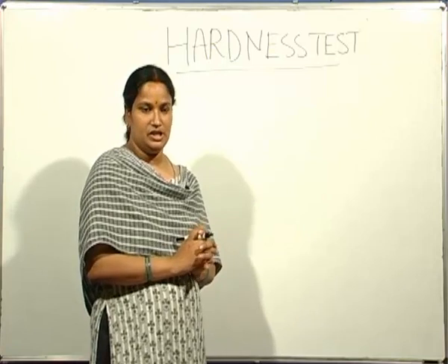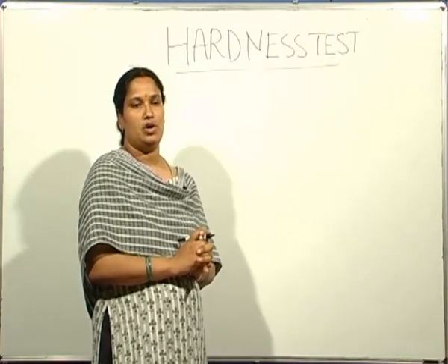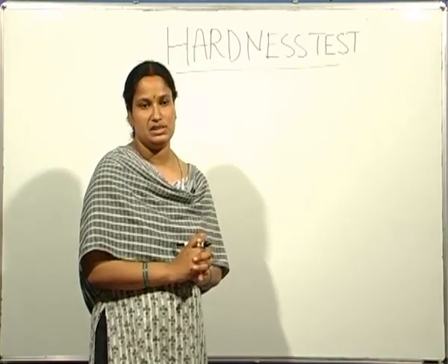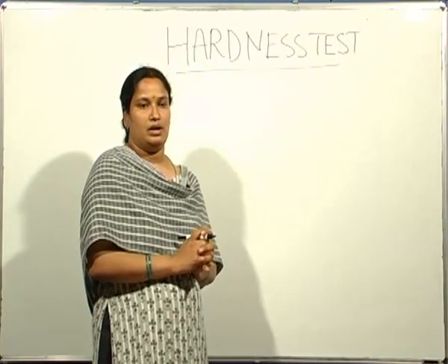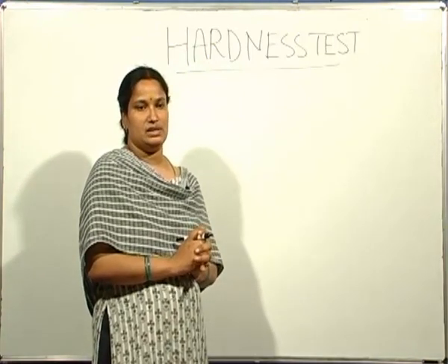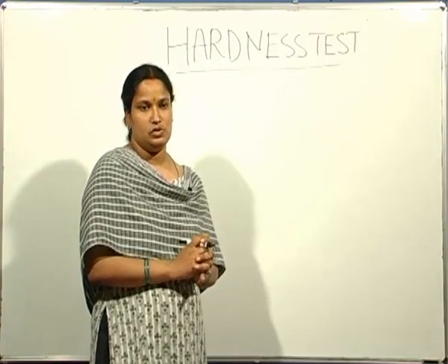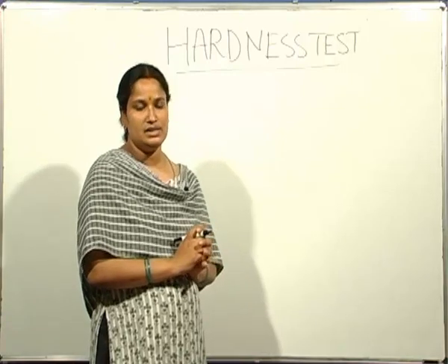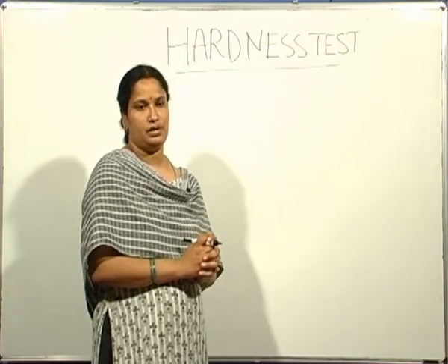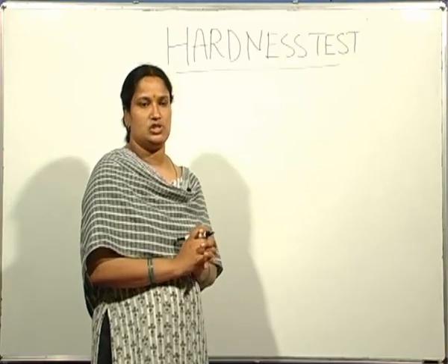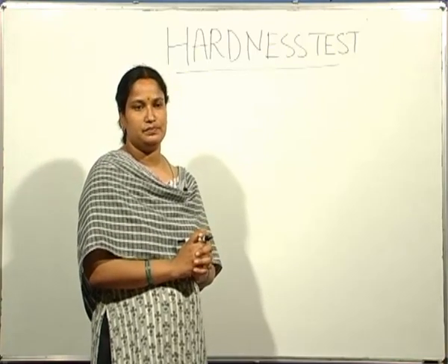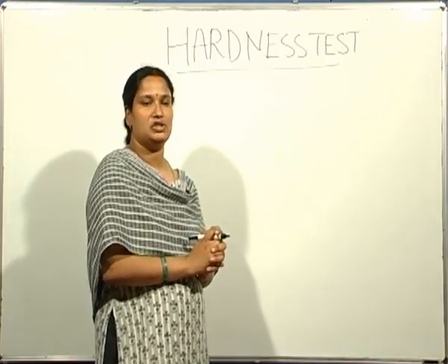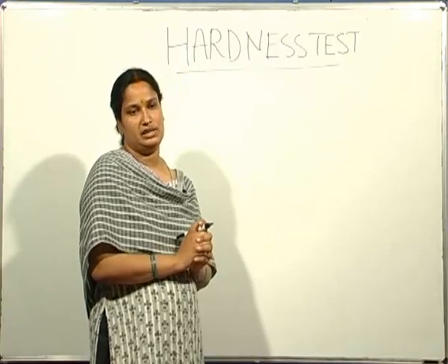We have seen the tension test, torsion, impact. All these are different tests to characterize the mechanical properties of materials. In evaluating the mechanical properties, the specimen has fractured. So these methods are destructive in nature, whereas the hardness test is non-destructive. It does not destroy the sample or the specimen. So this is one of the advantages of the hardness test when compared to other mechanical property tests.